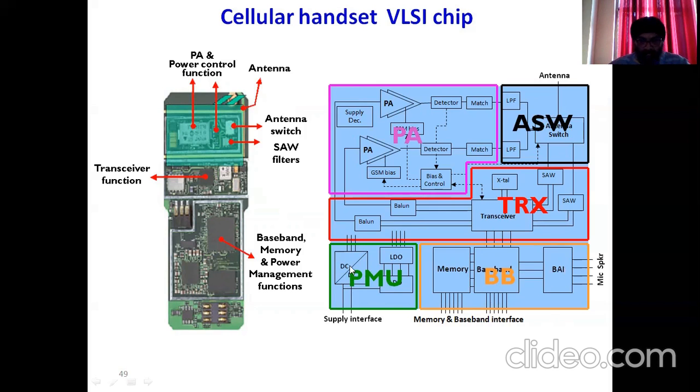So this DC to DC converter actually converts this DC value, which is received as input from some battery or something, and converts it into different levels. So this DC to DC converter converts, let's say, 5 volts from the battery, 5 volts to 1 volt and sends it to here, 5 volts to 1.2 volts and sends it to here, and to 1.3 volts and sends it to here, and so on. So these DC to DC converters are used in integrated chips, and let's say for this mobile phone handset, we can have about a dozen DC to DC converters on a mobile phone. And all of these DC to DC converters are giving us variable outputs, so that different components or different modules in the handset actually receive the required value of voltages. So this is an important application.